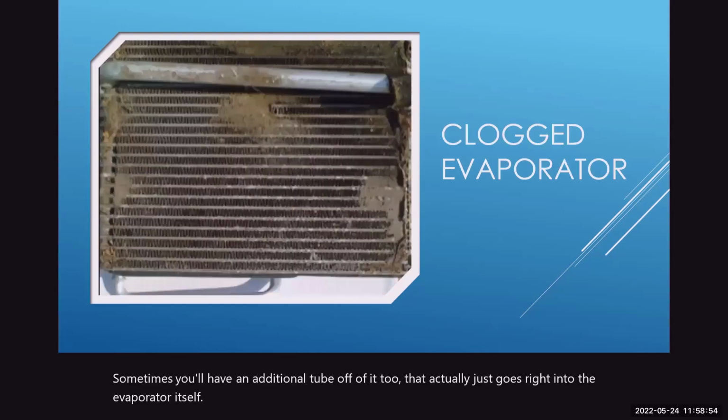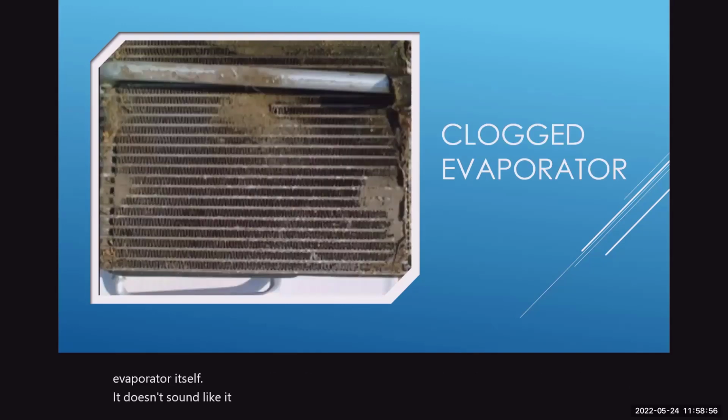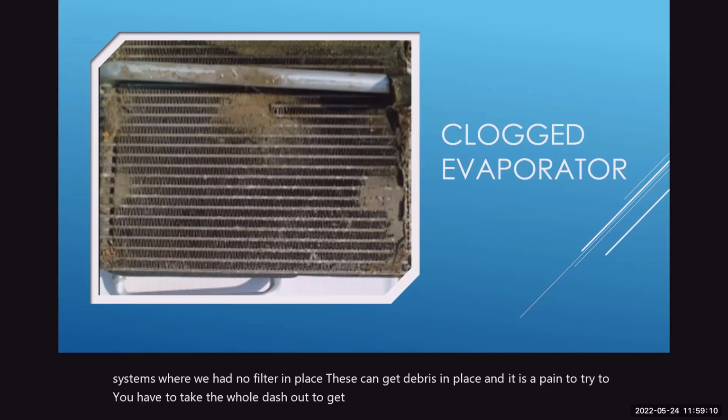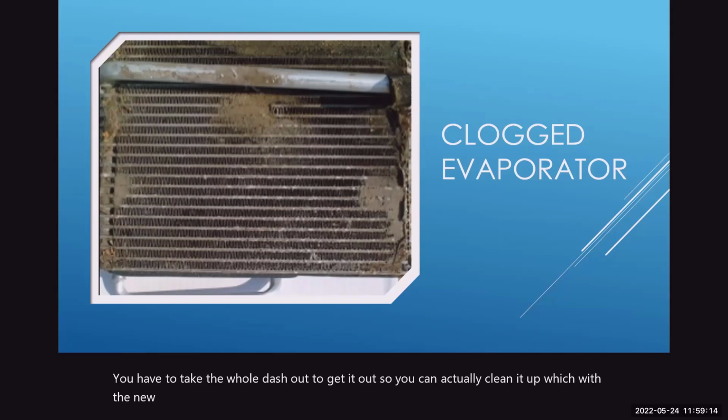It doesn't sound like it could happen, but the evaporators can get clogged, especially on the old systems where we had no filter in place. These can get debris in place, and it is a pain to clean, because you have to take the whole dash out to get it out so you can clean it up. With the new filter systems, where you have the filter in place in the direction of airflow, that won't be as bad.